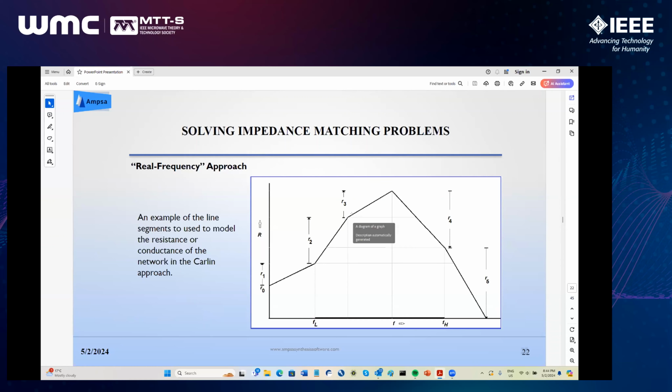So you will lose some accuracy there. Then you extract the circuit. Everything is fine if it's low pass or high pass, but if it's band pass, you may need transformers in that network. So when you extract the network, you may find you need transformers. So while it's good, it's not very usable for real problems. It has its advantages, but ultimately it's not going to do it for you.